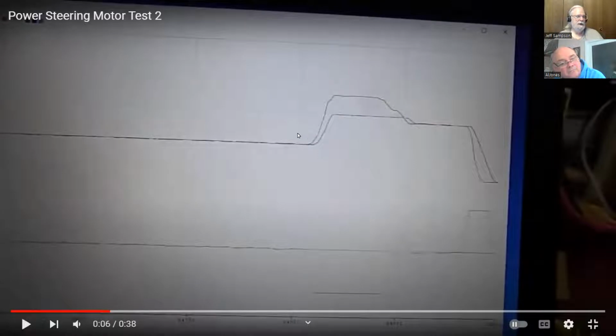So you can see right here, the red is the request pot. I turn the pot, and it comes up like this. But the motor comes over and says, "Oh, I hit my limit. This is my artificial limit that I put in." So it actually turns the motor power off completely at this point. I don't know why I've got 4 plots going on here. Anyway, if you try to go past that point, it just shuts the motor off.